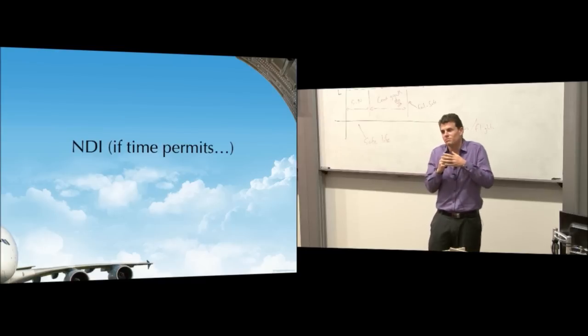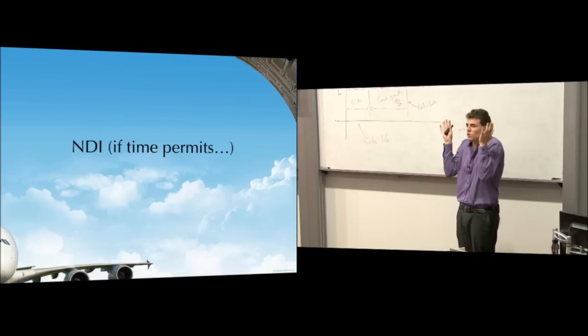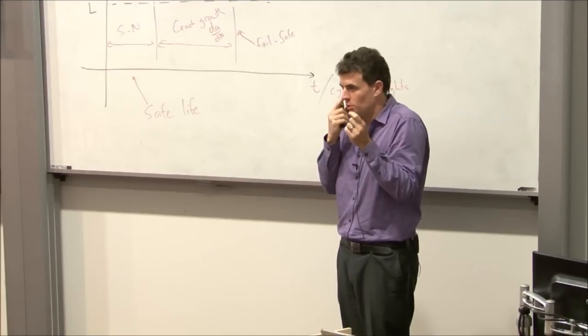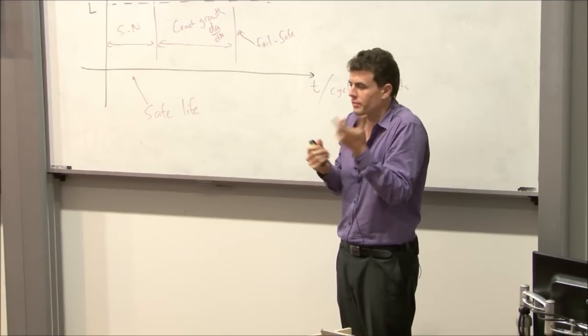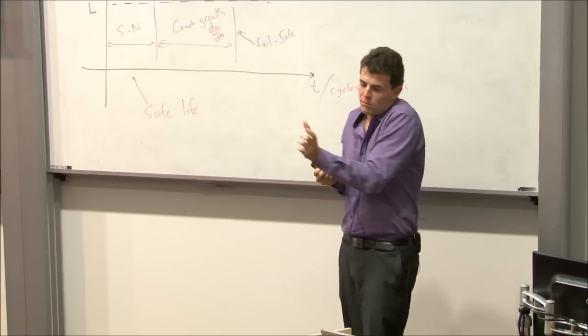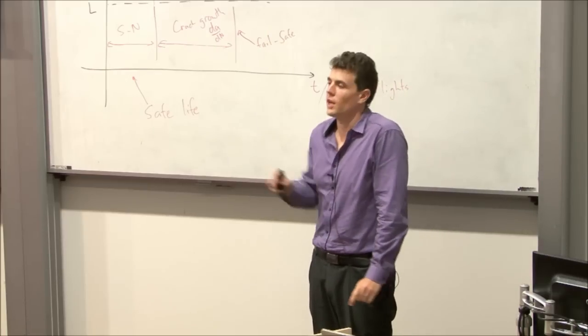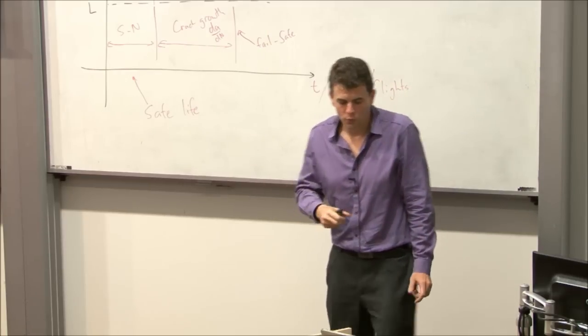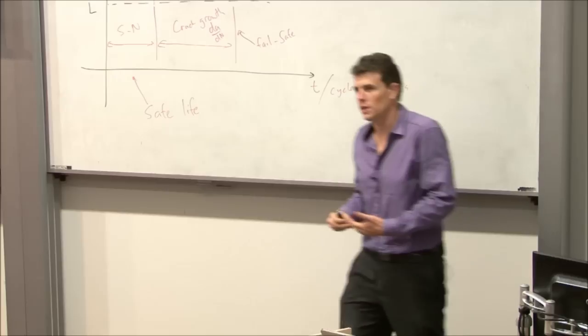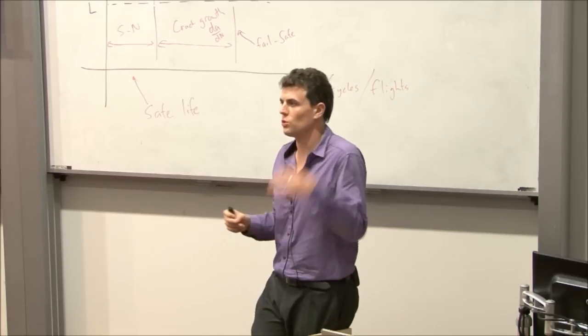but we can't really. That's just eyeballing it. We can't see cracks smaller than, I don't know, a few millimeters. Maybe something needs to be 50 millimeters before you're going to see it up on the tail of an aircraft from the ground. So we need better techniques to be able to see cracks, and we need techniques that can also look inside.